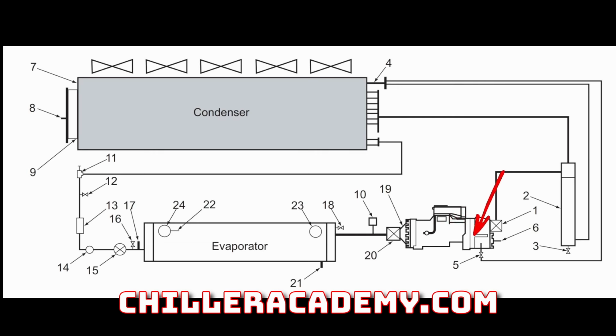We get huge amounts of CFM through the compressor without having to affect the motor and have any kind of speeding up, slowing down, anything of that nature. And we can dial how much the compressor is compressing very, very finely. And as you've seen with scrolls and with reciprocating, we just don't have that level of control. It's just not that refined. And from a control standpoint, short of the safety limits, it is that simple for these. That slide valve is just going to get pushed back and forth in order to maintain our leaving water set point as close to set point as possible.